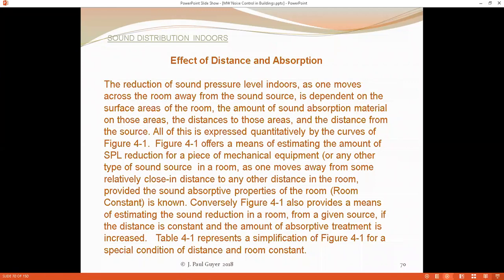There is also a certain amount of sound that will be absorbed in the source room by absorption. This is when there are soft type finish materials in the source room. The air molecules with the acoustic energy bang into these soft materials. The soft materials deflect on a microscopic level, and the vibrational or acoustic energy of the air molecules is reduced by absorption within the source room.